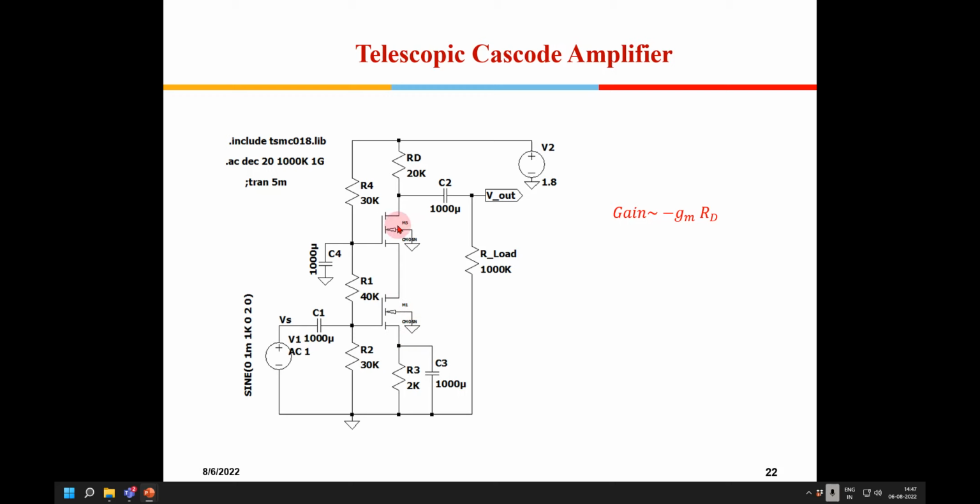Okay, and this is a common gate amplifier. We are only talking about one aspect; we will talk about other aspects also. So this is a current, and it is just current gain 1. Whatever current this is trying to pull, it will just pull like this. So this total voltage gain, since I am taking from here, will be minus GM RD.